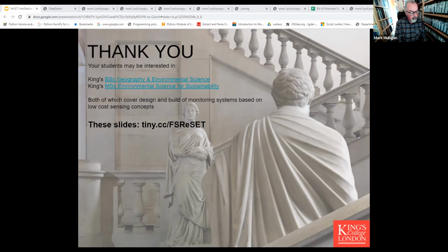The other element of maintenance is ensuring that you collect good quality data by ensuring, for example, that your rain gauge is not blocked with leaves, or your solar panel is not covered in gunk. Everything degrades in the environment. Solar panels, solar pyranometer sensors, you've got to keep them clean, to make sure they're collecting good data.